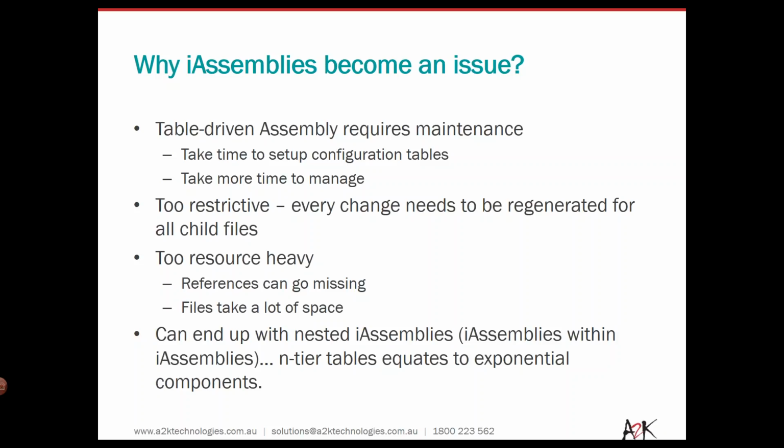So if you've got 100 members in one iAssembly and you place that into another iAssembly made up of 5, you can end up with 500 configurations. Okay, and then if you place that into another iAssembly, you can end up with thousands quite quickly. And so to manage all of that, it becomes quite, I guess, painful time-wise. So we need to actually do something about this, and luckily we have a solution in iLogic.